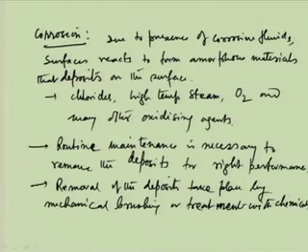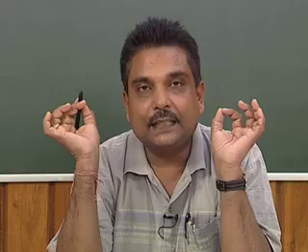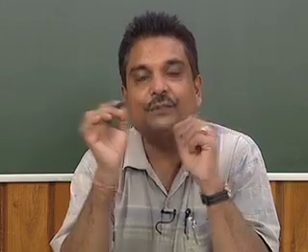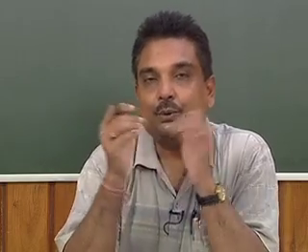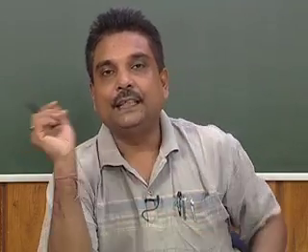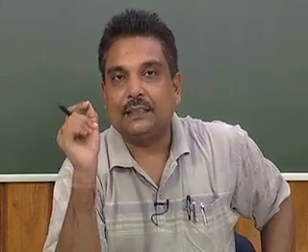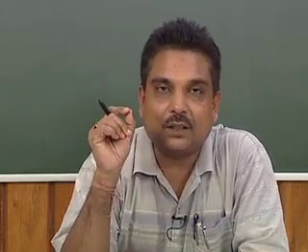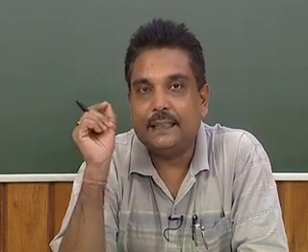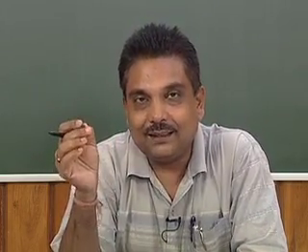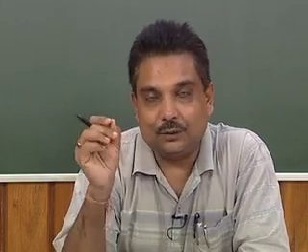Okay. Now, I will ask one simple question: in case of corrosive fluids to be handled, should these corrosive fluids be put in the tube side or in the shell side? The answer would be that we should put the corrosive fluid in the tube side. The reason is, if we put the corrosive fluids in the shell side, then it will corrode both the shell as well as tube surfaces.